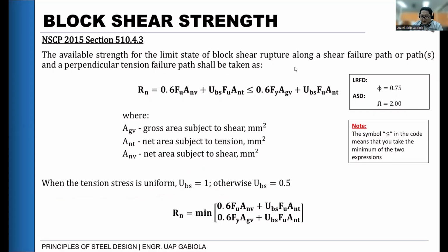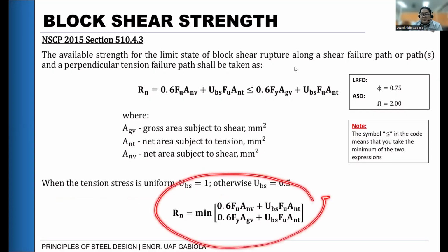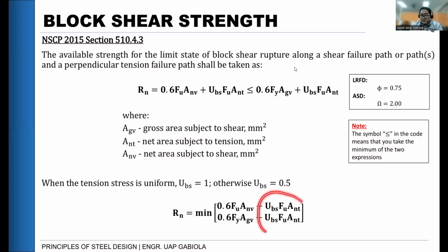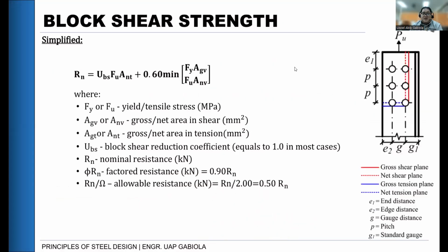But look at the simplified version. If you look at the second term in both equations, you will see that it is the same. And also, there is the same factor in the first term. So what I did is simplify this further so it's easier to memorize the formula for block shear. Okay? So now, what we will use for block shear is this.